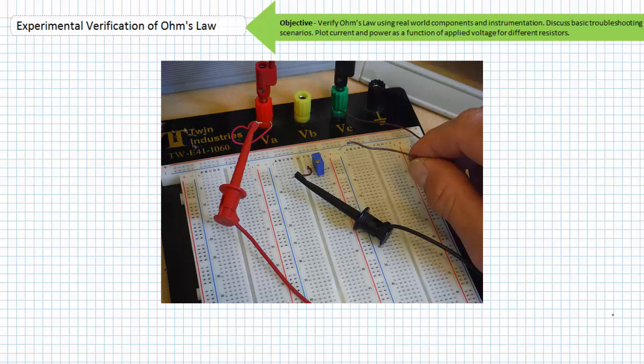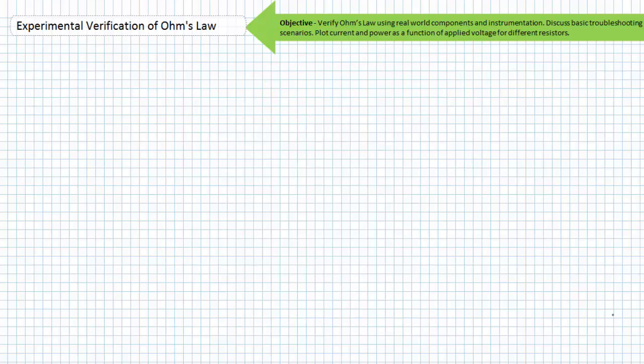Consider a voltmeter not placed across or in parallel with something, but rather through or in series with something. Voltmeters don't go in series. Voltmeters are modeled as extremely high resistances. And if we assume this modeled high resistance is an open, no current can flow through a voltmeter. Current stops. Yes, where you improperly place the voltmeter, there is a voltage drop. However, there is no current flow through an open.